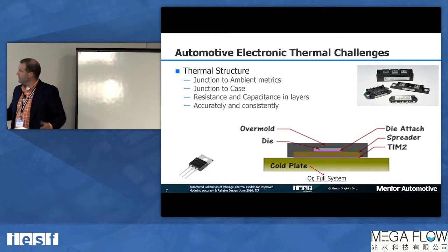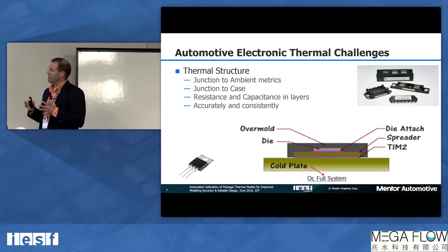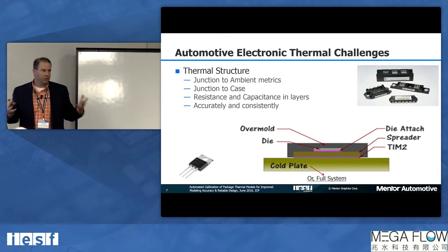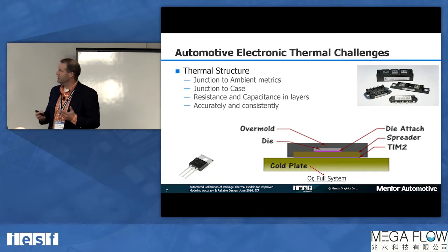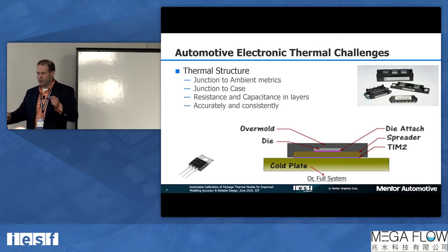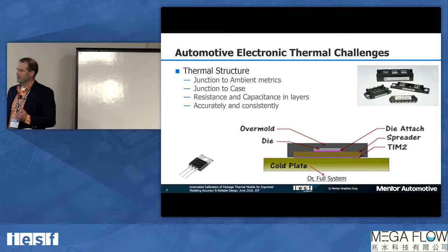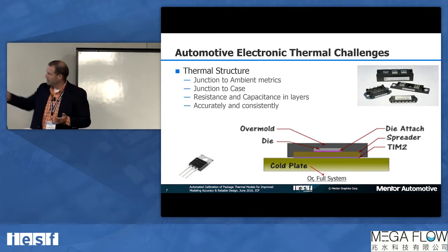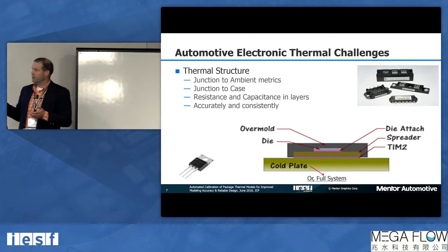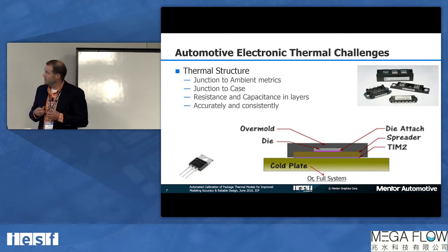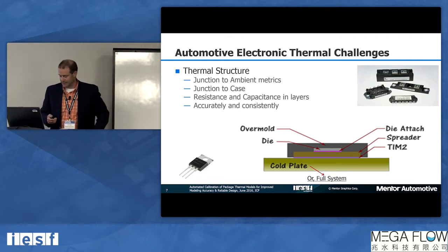So what is the challenge? It's to understand the thermal structure. What is the thermal structure? We've got some metrics you've heard in the industry, junction to ambient, junction to case, but those are one point in space and a temperature across, and they're really hard to define what the thermal characteristic is of a component or a component in a full system. With this hardware, we're able to measure the resistances and capacitances in layers and do it accurately and consistently.